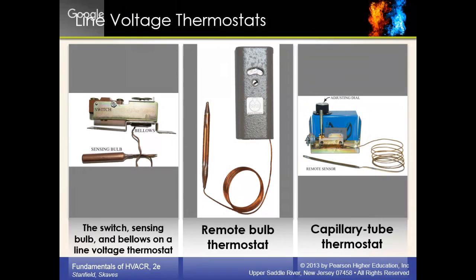So we have two different kinds of pressure switches. We have the pressure switch like we have right there that's an unsettable one. Once it gets to this PSI, it's going to pop, and it doesn't care what's going to happen. I would consider that a dumb pressure switch. And then you have what we looked at, these guys over here on the wall with the adjustments.